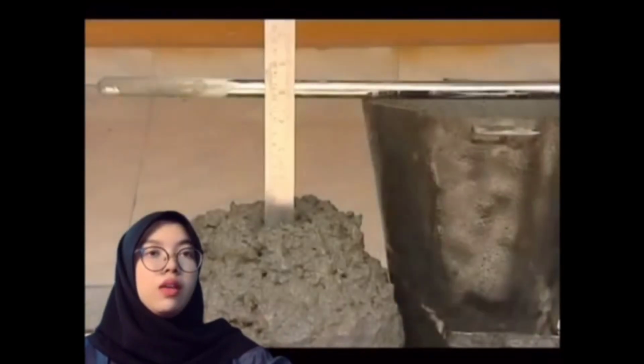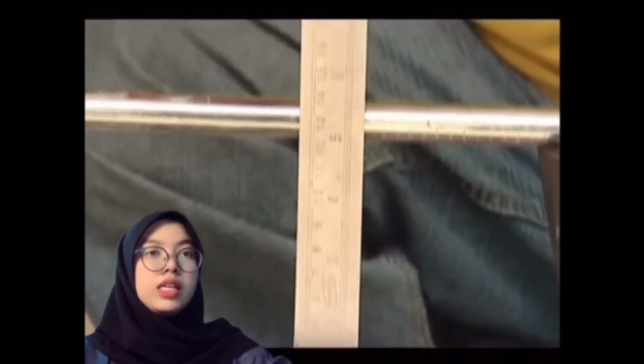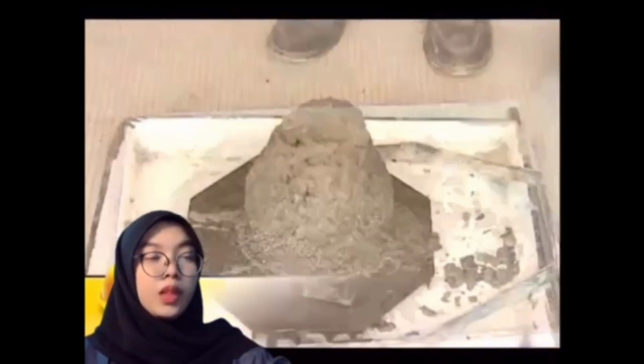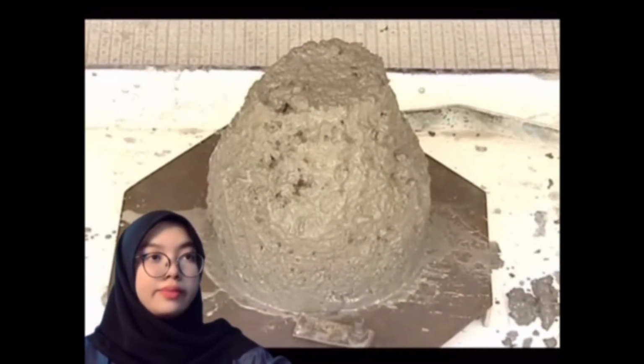The difference in level between the height of the mold and the highest point of the subsided concrete is measured. The subsidence measured is the slump of the concrete. The slump may be either a true slump, a shear slump, or a collapse slump. The true slump is the desired form of slump that we require.